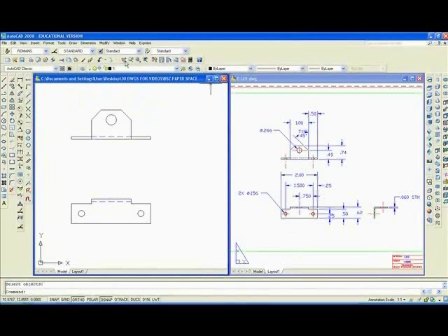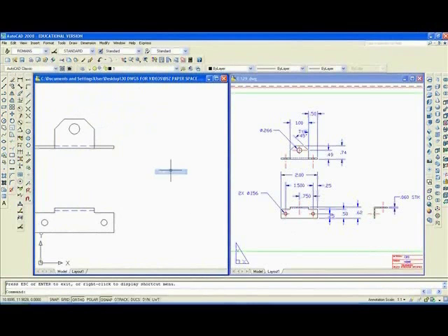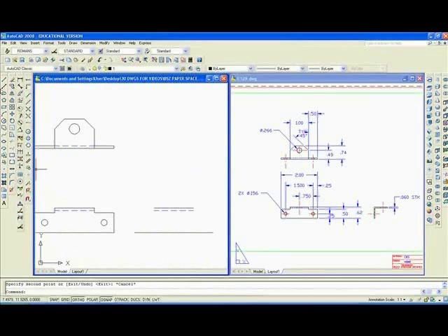Perhaps the next thing to do is to pan over and draw the right side view. So I'll copy 3 lines here and drag them over. Draw another line down here and offset O, enter, 0.74, enter.